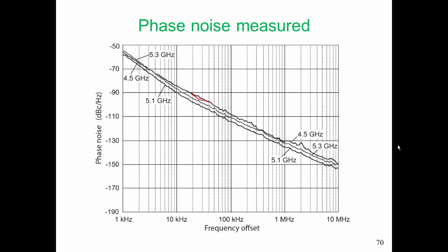That's the curve at 4.5 gigahertz, and it is fairly standard to compare oscillators by looking at the phase noise at 1 megahertz offset from the carrier. So here our phase noise, 1 megahertz offset from the carrier, is minus 130 dBc per hertz, which is a very good result at 5 gigahertz, or in this case 4.5 gigahertz. We do better even as we go to higher frequencies. So here is a VCO that has a very wide tuning range and very low phase noise, state-of-the-art phase noise.